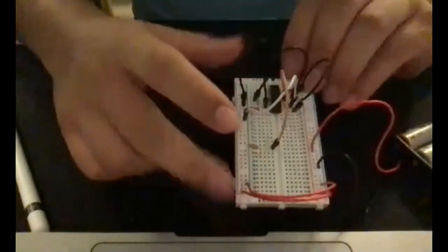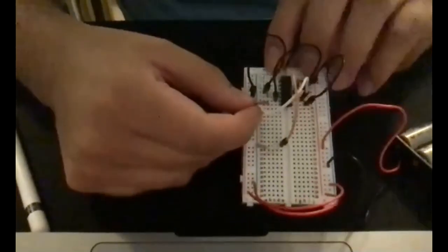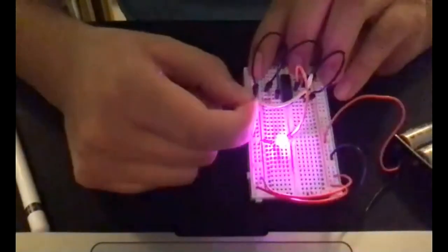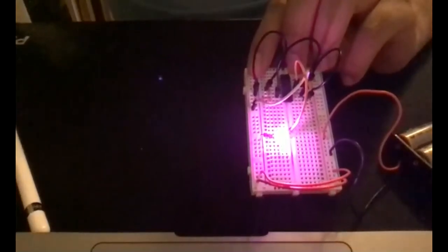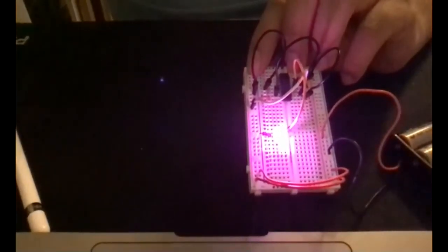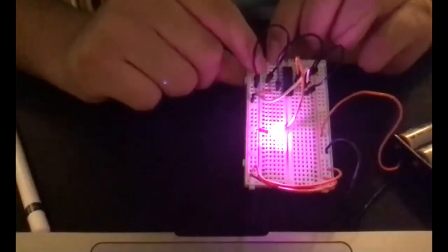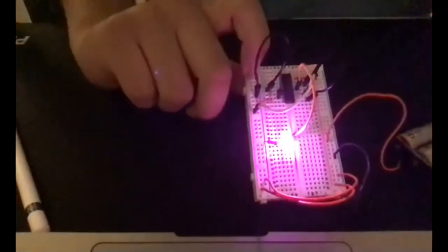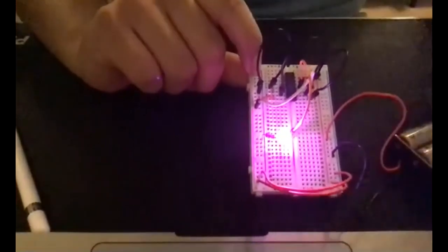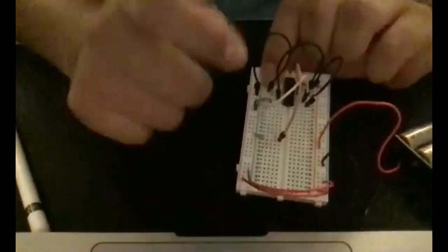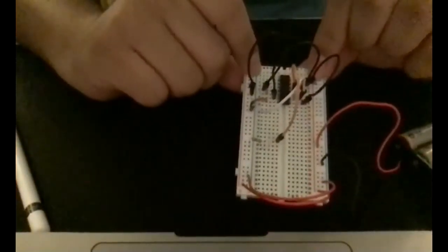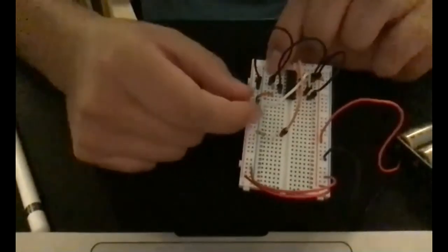And now our inputs are 0, 0. So as soon as we input 0, 1, this should turn on. And we see that that is the case. So for OR gates, if the inputs are 0, 0, you should have a low, which means your LED is off. But if you have an input of 1, 0, 0, 1, or 1, 1, then your output should be high, meaning the LED turns on.